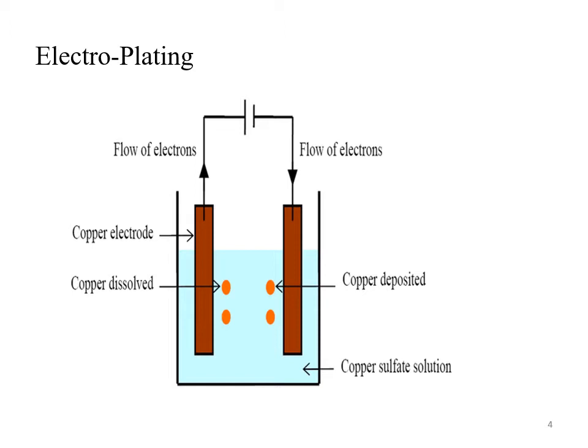causing penetration into the target surface and removing the material, just like plowing of soil in a farming field. Similarly, the abrasive particles penetrate into the target surface and plow out the material from the workpiece. In case of water jet machining, the water jet itself, with very high velocity or very high kinetic energy, causes the cutting of material on the workpiece.